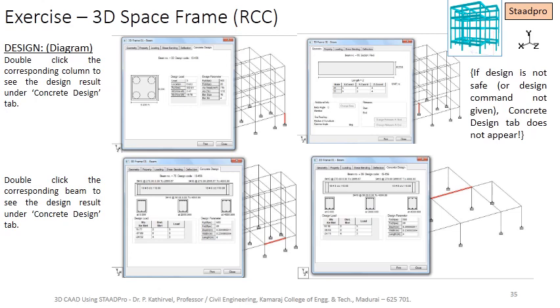To view the design result of a beam or column in between the levels, you can go to the front view, select that level alone, right click, click New View. You can get that level alone. Now you can double click the beam or column to get a better visibility of the design results. It is once again emphasized that making the members safe depends on the person who designs the model, to redesign by changing the dimensions of the members or grade of concrete or grade of steel.